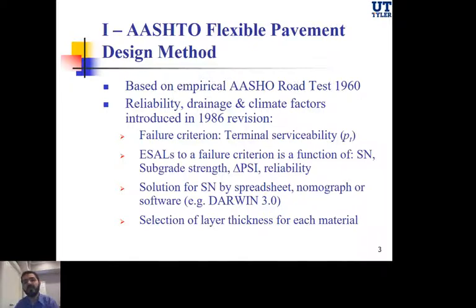They related the pavement design to reliability level, which means if I can design the roadway with high reliability at, let's say, 99%, most of the time this pavement is going to last for what it's intended to. Let's say if I'm designing it for 15 years, it's going to last for pretty much 15 years. But if I'm designing the pavement with a reliability level of 50%, that means there's a 50% chance that we're going to reach the 15-year design life, and a 50% chance that this pavement will have premature failure.